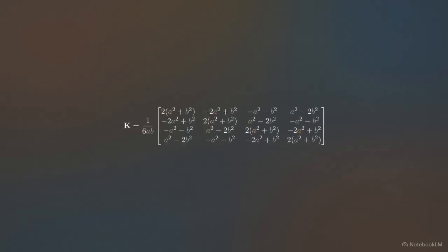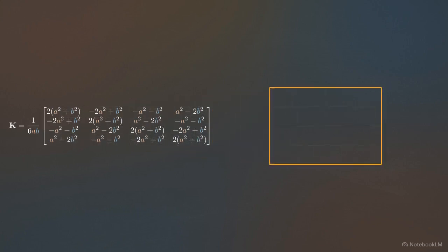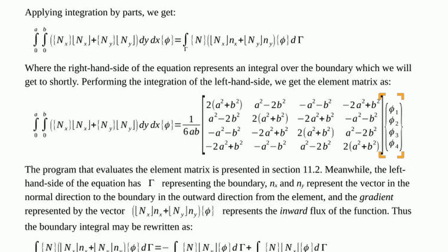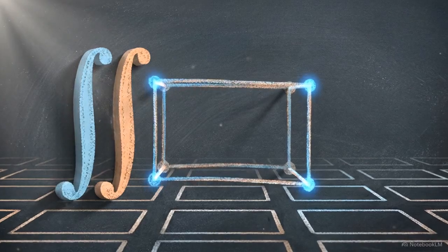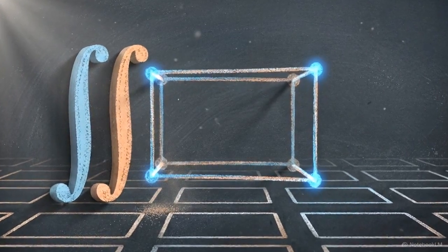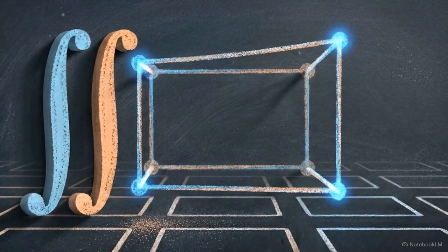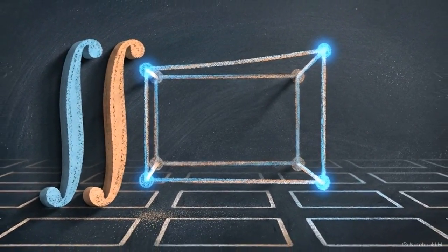Every cell inside this matrix is dictated by the physical internal geometry of the rectangular element, and it is multiplied precisely by the column vector containing our four unknown nodal potentials. This evaluated 4x4 grid is the element stiffness matrix. It defines the intrinsic internal resistance, or flow capacity, of the rectangular geometry itself.